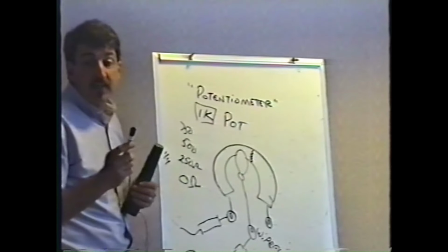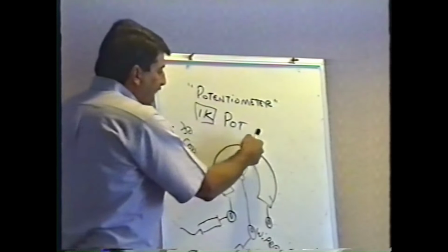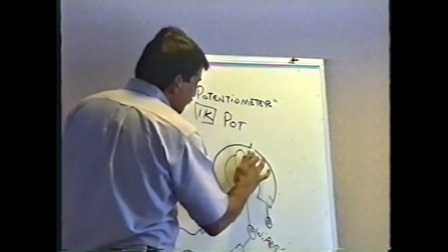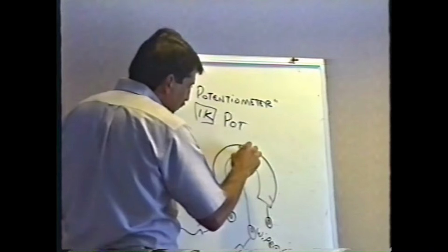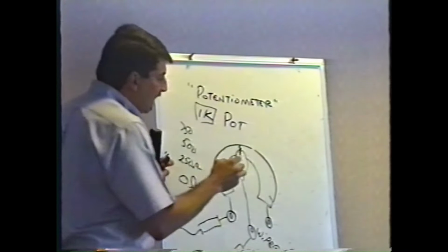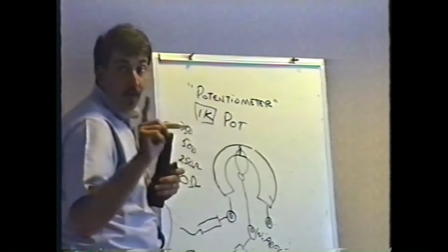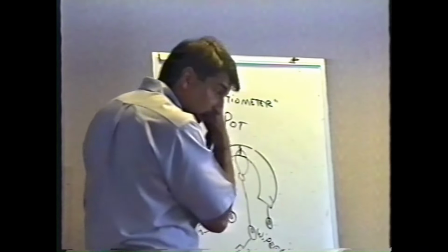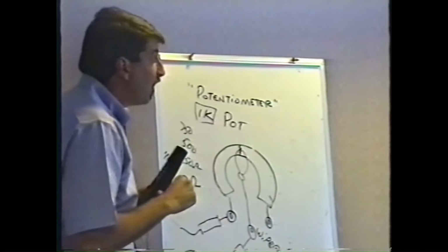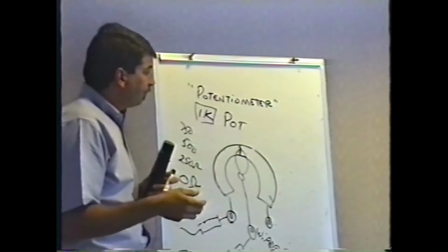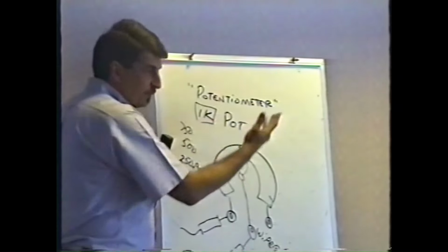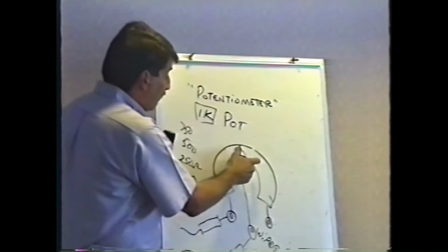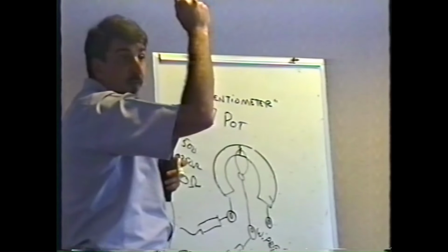Anyway, one of the things that can go wrong with a pot is that the resistance element can crack on these carbon pots. This is especially common where the wiper has been in one place for 7 years. It's an especially common problem on the type of monitor that's in your Vigilante game, Shirley, and that's in this monitor here. There's a potentiometer on these things that it's called black level. It's a brightness control. And it sits in one spot for years and years and years, and eventually it cracks and causes no picture. And then you barely move the pot, and it comes back on full blast.